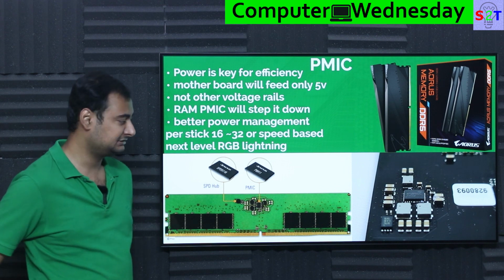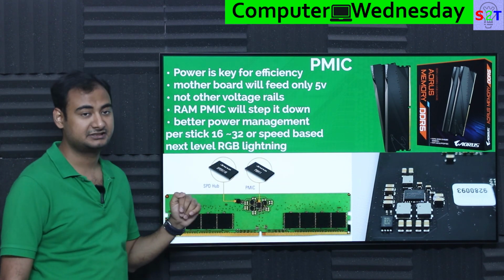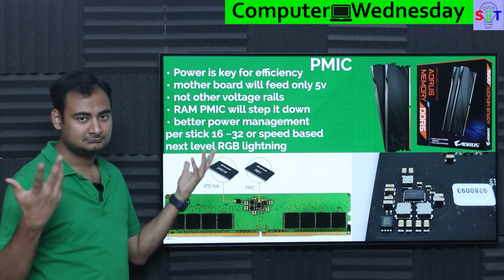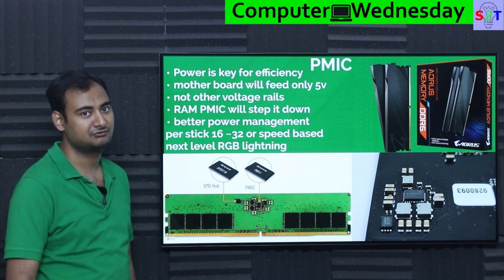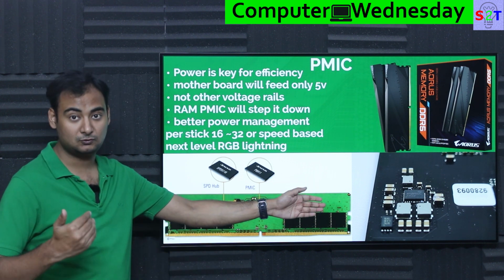So the first biggest change that you will notice is this puppy, that is the PMIC, Power Management Integrated Chip. Now this puppy is there for power management because, well, power is the key to efficiency. The more power efficient you are, the less heat you produce, the less heat removal system you need. So this is one thing that you have to do. So how does this differ from the old generation?